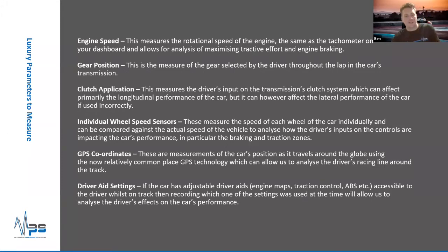Also with a GPS system, it becomes really easy to break your data down into laps. We can put in an artificial line across the track using GPS technology, and every time you go across that line, it signals to the data logging system that you've started a new lap. I'll cover this later, but when we look at driver data, it's really beneficial to have on our screen lap by lap and compare one lap to the other as we analyze the data. So a GPS system is really recommended if you can get a system that suits it.